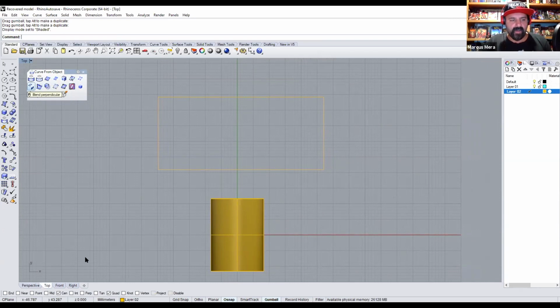I'm going to now click on, remember on snaps? Well, in this case, I like to use the middle on snap. I can turn off the center on snap. These are left clicks, by the way. I'm left clicking to turn on and off. Right click just deletes everything and just chooses the one that you right click on. So I'm going to right click on mid just to make sure I stay on mid.